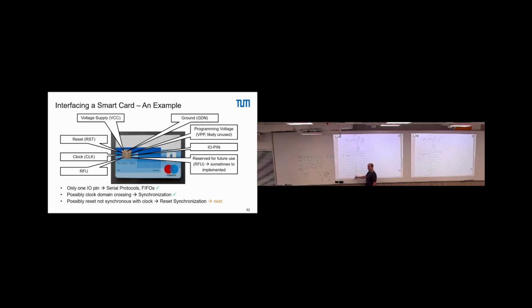I draw it here. That shifts it to the right of this clock edge. Nevertheless, it is independent of the clock. It follows just the signal. The reset is released at that point. Yes? No? Because there's no flip-flop in between, right? So there's no clock involved. But the reset